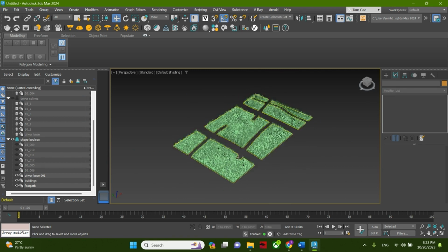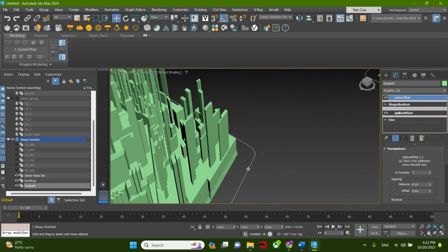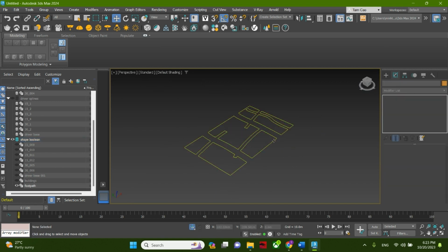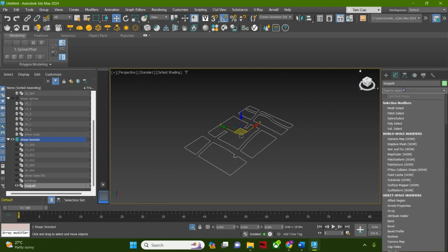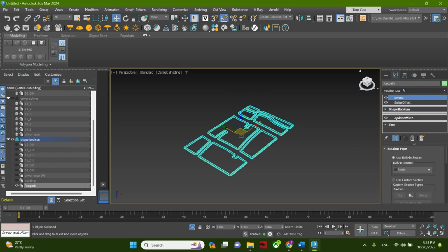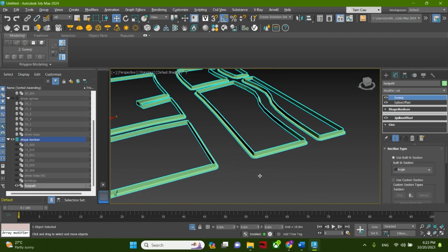For the footpath, if you select the footpath layer, I'll just go here, and then I select the selection, and I'll say sweep. Actually, I'll go extrude. Oh no, sorry, sweep. Yep. Yeah, I think sweep. Okay. And then you change the settings, scroll down here.